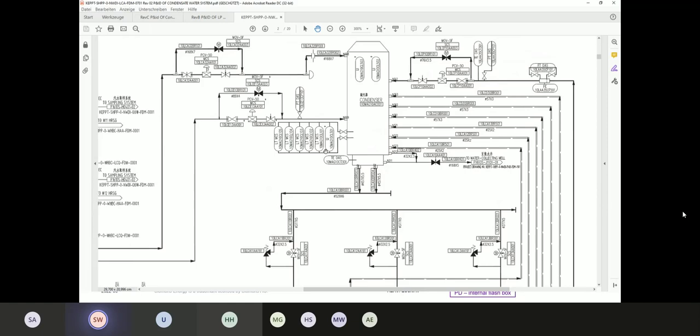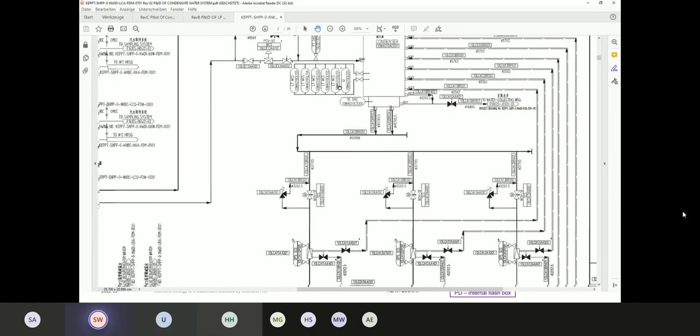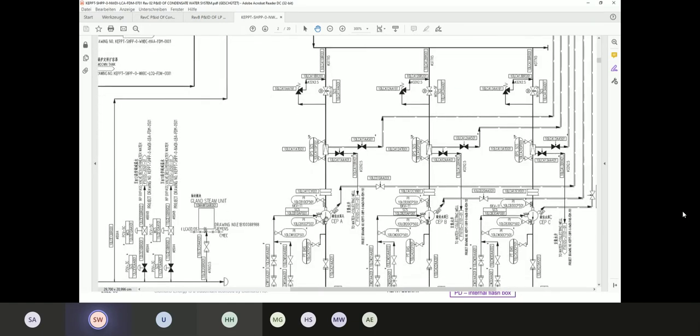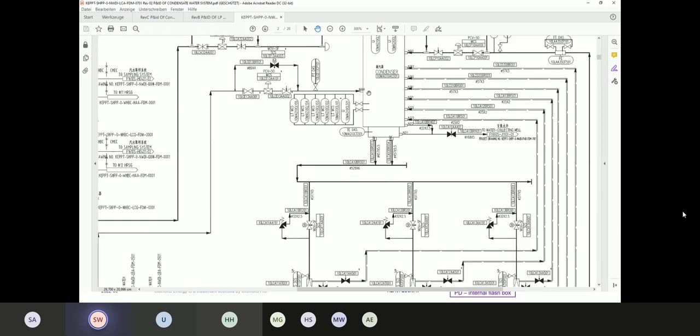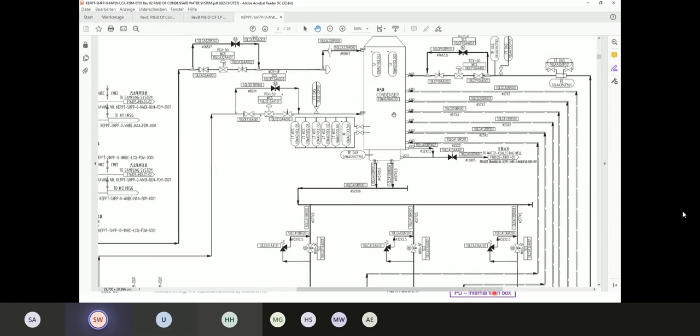So it should go from the protection, from the levels, to the enable operation of the pump, and the enable operation will just be coming when there is a certain level inside the condenser. This is the normal behavior over here, so that you have the suction pressure for the pump, in this case, over the hot well level or condenser level.